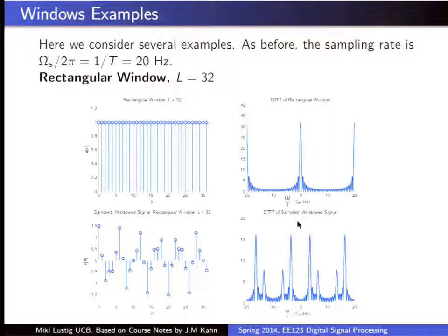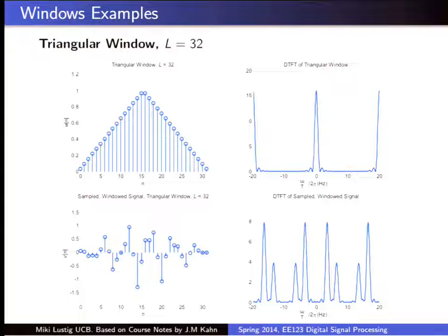You want to try a triangular window? You want to try? Yeah. Let's try. Okay. So I add a triangular window. If you think of what a triangular window does, it tapers, it basically makes a smaller window, but it kind of still uses some of the far away samples. I mean, it tapers off, right? So it's an effective smaller window. That's why things become wider. Okay? But then there's no sharp changes, so the ripple decreases. It's another interpretation.